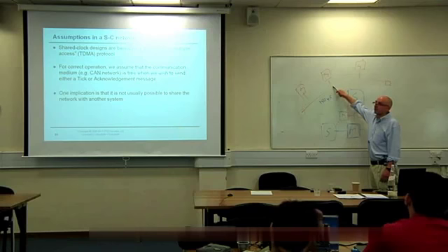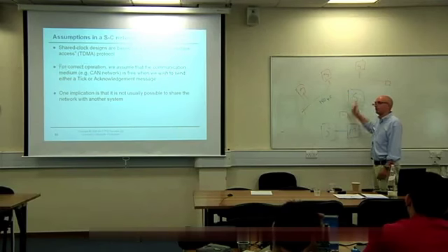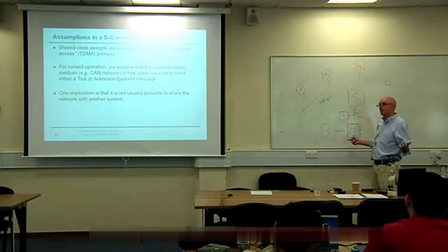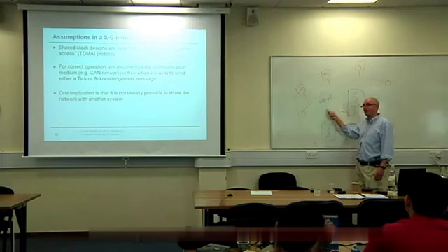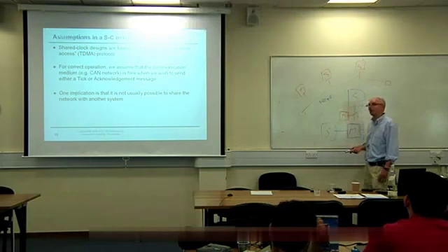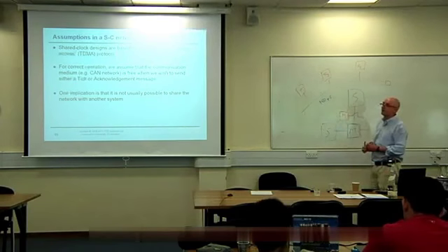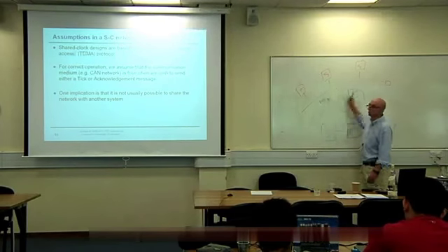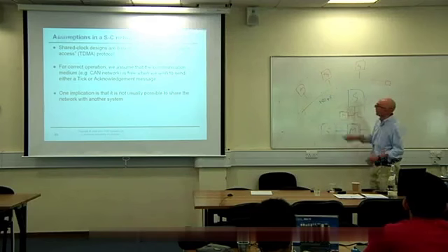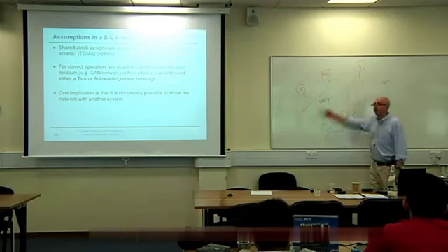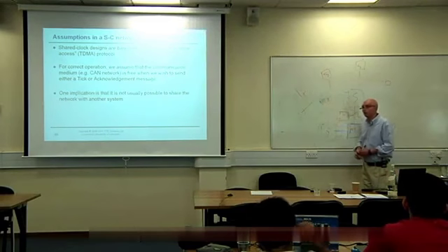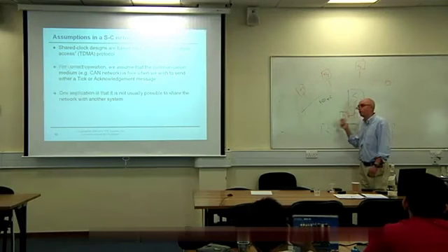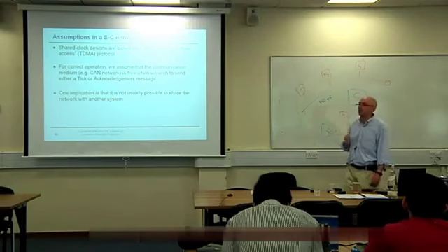That's big time late. Once you get to distributed systems, saying 1 microsecond is bad news, but it's difficult to get to 1 microsecond of jitter. You take it into the distributed world, 200 or 300 microseconds of jitter is easy to get if you just don't take control of these messages. So you need a private data bus here, or to have control over this, or you can't control the timing in this way. So you need to have control over the messages.